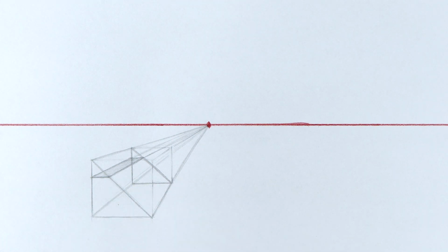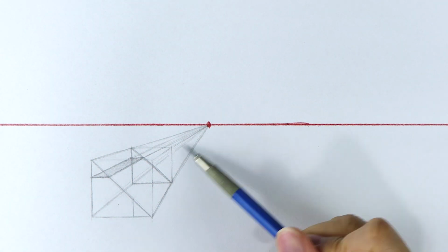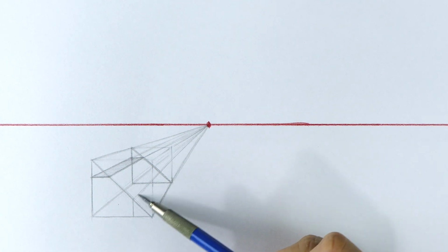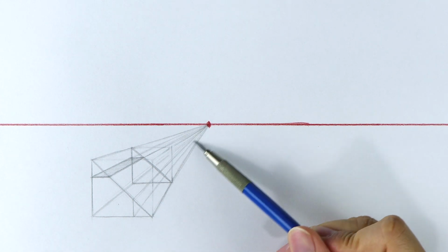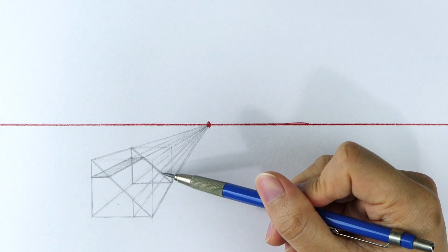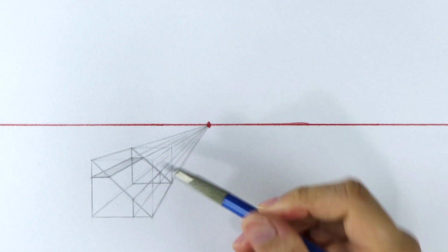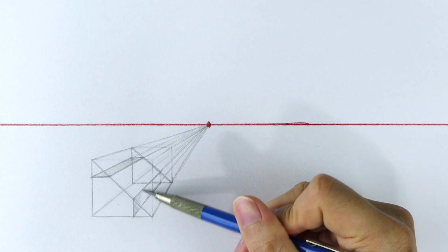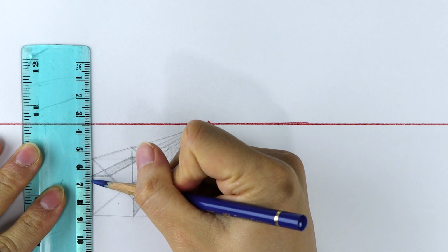Next, let's say we want to slice off the other tip of the prism as well. Again, we'll draw a vertical cut line onto the front plane. Connect the two corners that were just created to the vanishing point to create the depth lines. And the point where the depth lines intersect with the back edge is where the rear cut line will be. And that's our shape. I'll clean it up with this blue pencil so it's easier to see.